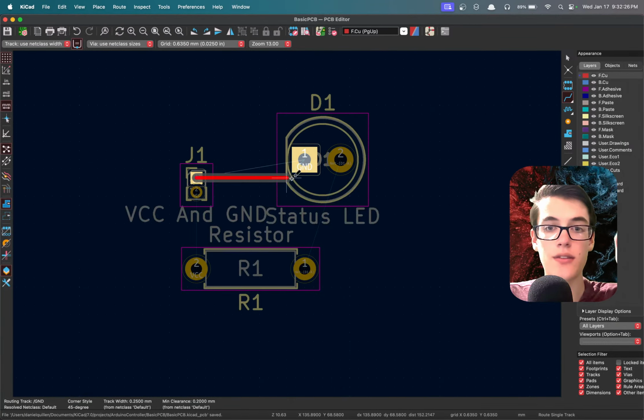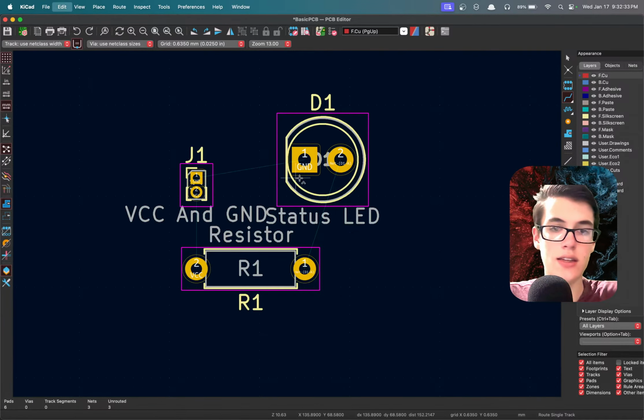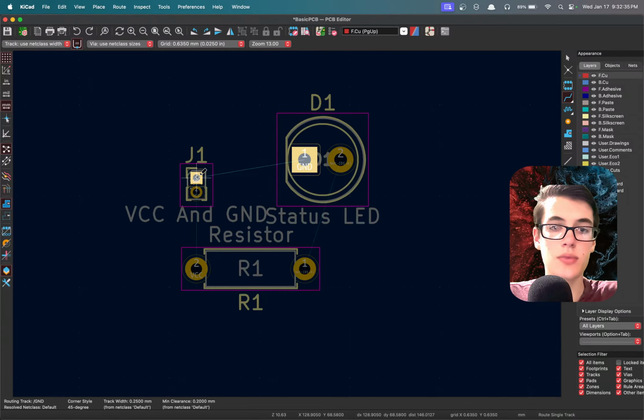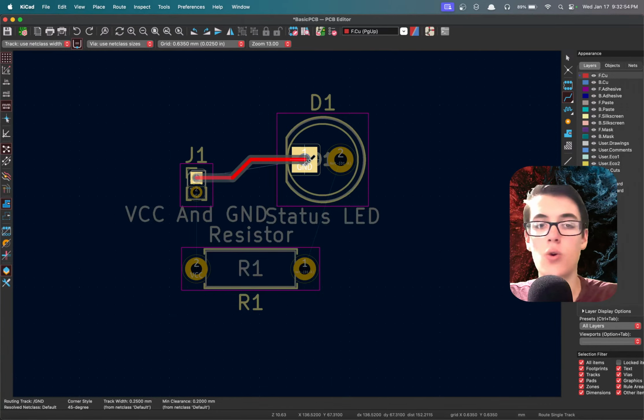One thing you want to be careful of is you don't want a 90-degree angle like this. Now, KiCad typically won't let you do that, it'll try to have that not happen. So if I just click and drag, it'll do a diagonal automatically, but if you click down, then it'll put a corner there. So you can see this part right here over on this side is going to be dimmer and the part on the other side is going to be a little bit brighter. So then it'll try to preserve the corner location that you set. It won't always be able to, but it'll try to preserve that and still make something that works.